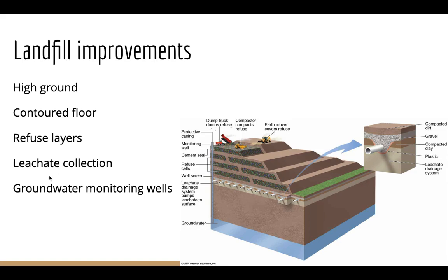And in addition to that, you also want to have some groundwater monitoring wells, right? So this is making sure that leachate is not actually leaking into the groundwater underneath the landfill, right? So being able to monitor whether or not you're having any cracks in the bottom of your landfill.